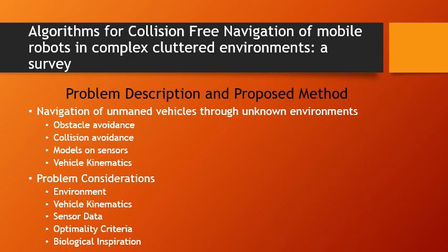In the environment, there are multiple scenarios that can exist that are cluttered with multiple objects or static environment. Hence, a vehicle is spatially modeled as either a point or a polygon for all approaches. Polygons are supreme as they are commonly used for tightly maneuvering around closely packed obstacles. In the section on vehicle kinematics, many unique vehicle robots can be considered. Hence, holonomic, unicycle and bicycle are introduced.